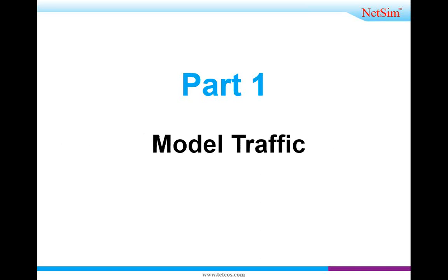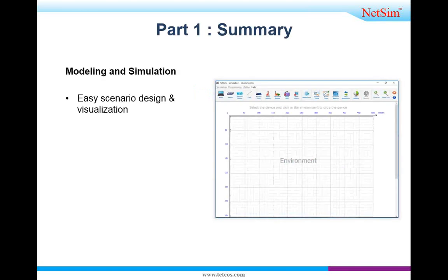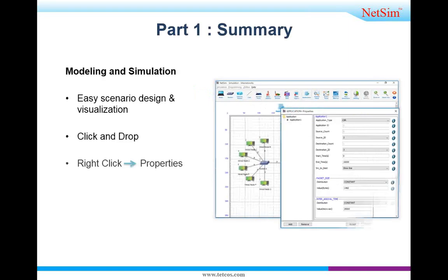Now model traffic. In model traffic, you can create traffic like email, HTTP, custom, CBR, various kinds of traffic you can generate on any node. So just to show the packet movement, we can generate this model traffic. Then simulate your network. After the creation and modeling, you can simulate the network and see the result. In simulation, you have to give the simulation timing.